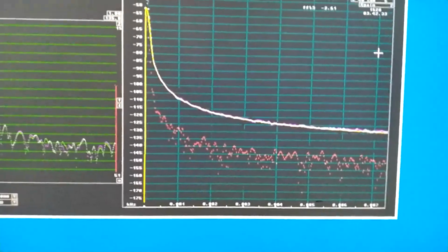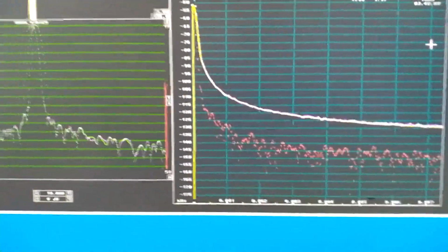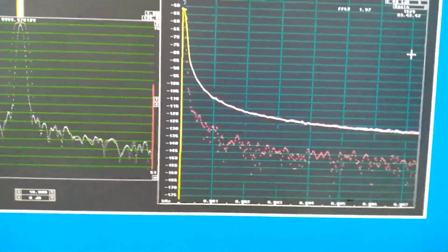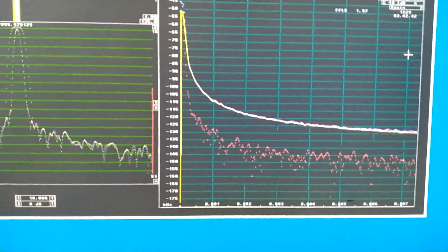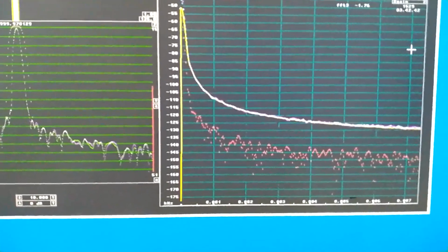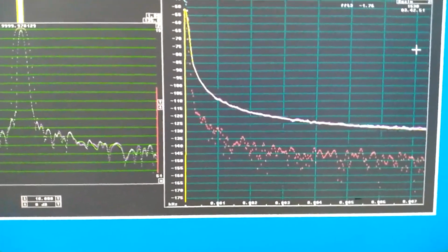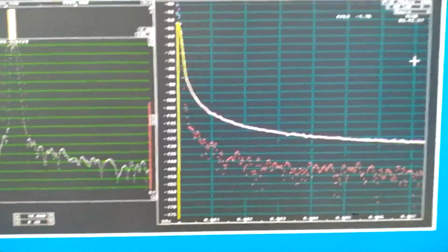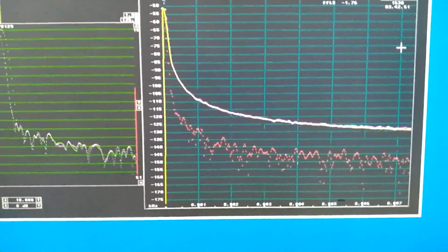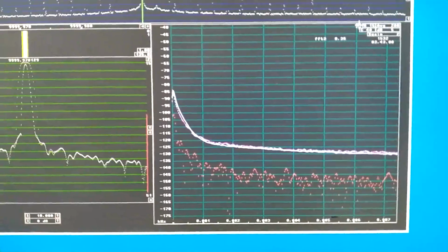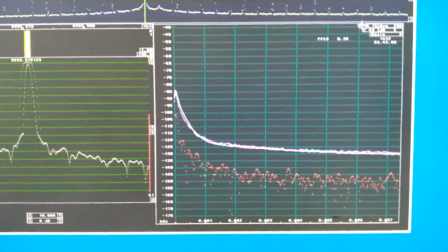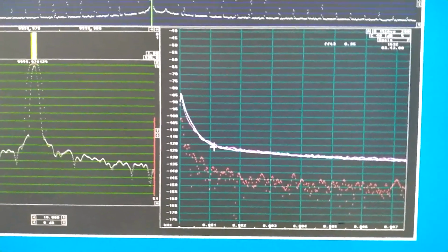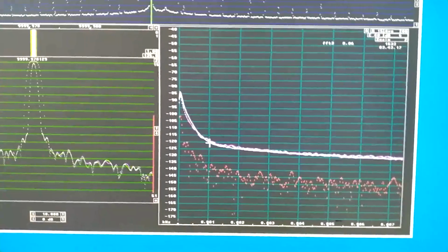After a restart and a couple of hours, I see, as expected, that the 1 hertz sideband phase noise is minus 108 dBc per hertz, just as expected from previous measurements. And here is the amplitude noise. It is much lower, minus 120 at 1 hertz.